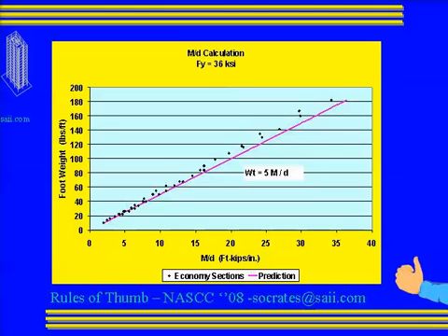When I give this again, I'm going to have the other slide as well, where I developed it way back, where you put every steel shape that is in the steel book, and then you put this equation on. But this one just has the economy sections on here, so you can see that it's a conservative approximation, and the heavier the moment, the further away you get, but it's always on the conservative side. And it's an easy number to remember.